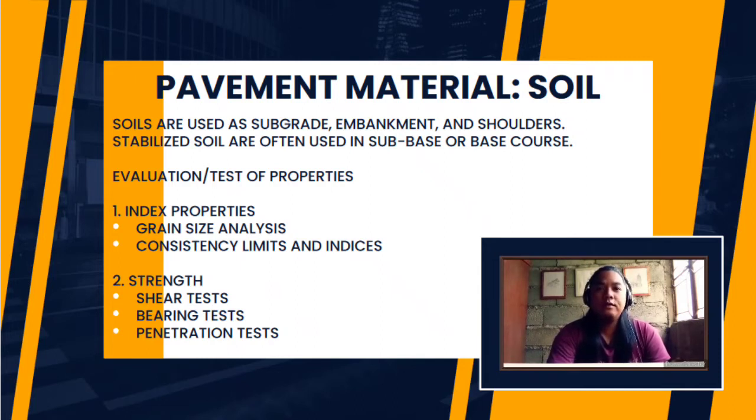In soil, we have two evaluations or tests of properties. Una dito yung ating index properties. We have the grain size analysis and consistency limits and indices. For grain size analysis, we have two methods na ginagamit. Una, yung sieve grain size analysis wherein it is capable in determining the particle size ranging from 0.075 millimeters to 100 millimeters. And we use hydrometer grain size analysis naman for the particles that are less than 0.075 millimeters in size. Whereas particles na mas malalaki sa 100 millimeters can be